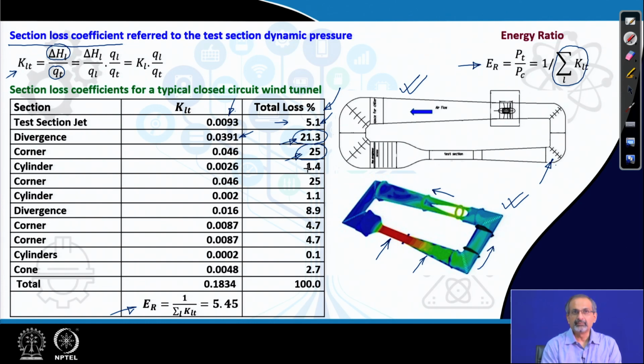So, the flow is still at a fairly high velocity, and incidentally the losses that are being incurred are also on the higher side. Of course, as you move through the diffuser, the losses are in general higher because the flow is going through an adverse pressure gradient, and there is always a tendency of minor flow separation occurring as the flow moves through such an adverse pressure gradient.